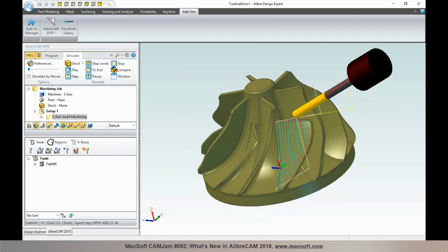Just a clarification here. When we are talking about 5-axis, it was already mentioned, but I just want to emphasize it. In our previous versions of the AlibreCAM product, we were able to do 5-axis index machining. What that means is we're able to rotate the part or the tool in different orientations, then lock it, and only move the X, Y, and Z axes to machine like a 3-axis or a 2.5-axis operation. We call that 3+2 machining, you might have heard of that term, or index 5-axis.